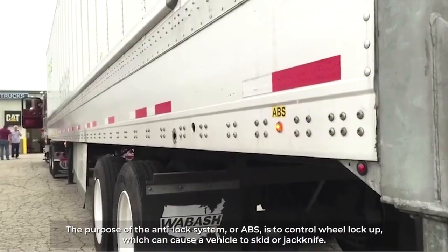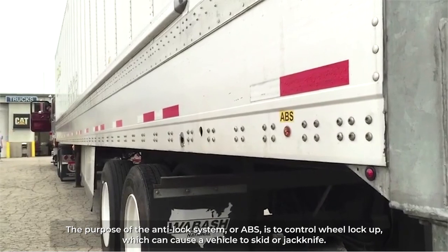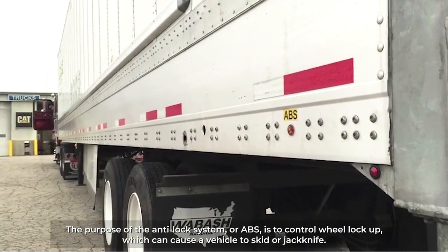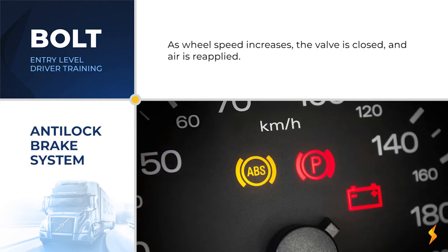The purpose of the anti-lock system, or ABS, is to control wheel lockup, which can cause a vehicle to skid and possibly jackknife. This is accomplished by an electronic system which senses the speed of each wheel. When the wheel speed sensor detects an imminent lockup, a valve is opened and air in the chamber is released. As the wheel speed increases, the valve is closed and air is reapplied.